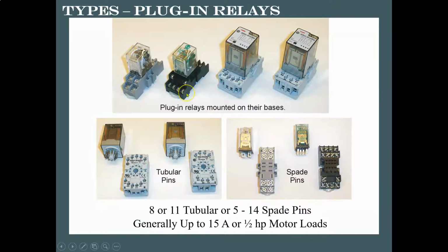So these ones are great for if they burn out, something's wrong. You literally just have to unplug it, just pop it out. You don't have to unscrew any wires or do anything, and just pop a brand new one in. So they're very handy like that. But again, they're not going to be used for anything much more than half a horsepower motor loads, right? Usually up to around 15 amps max.